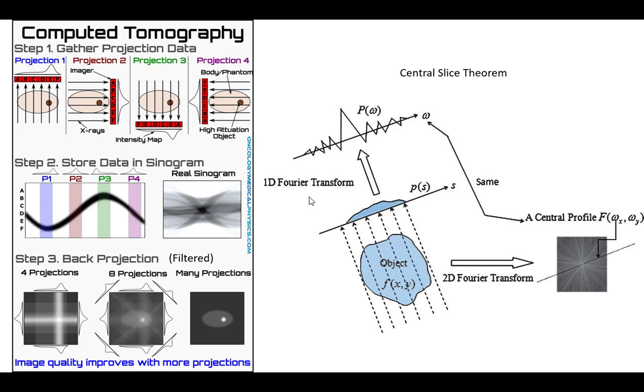This is not, they called it back projection. It's actually filtered back projection because you have to filter it to remove the smearing, which is in essence adding low frequency because it's constant all the way across. Right? So regular back projection creates huge amounts of low frequency noise. So you put a high pass filter on it, that's the filtered back projection. You get these sharper images. Right? And as I go to more and more projections, it just gets clearer and clearer.